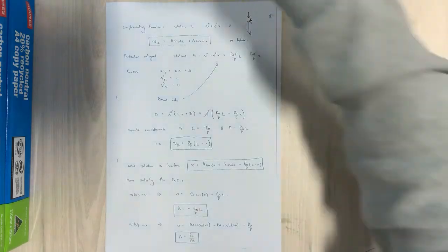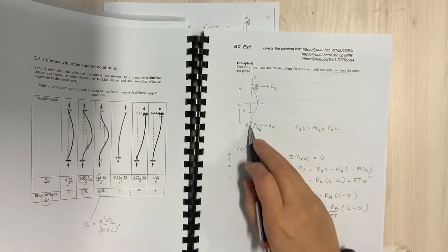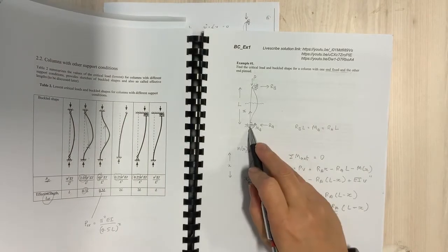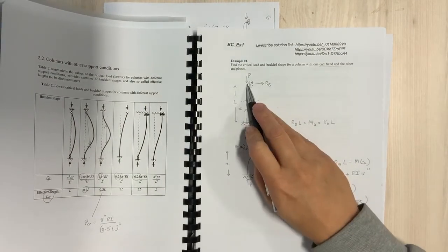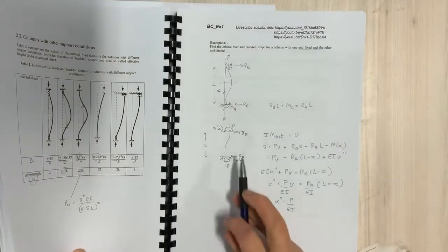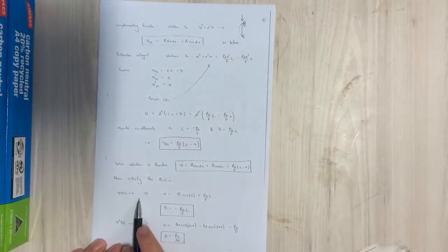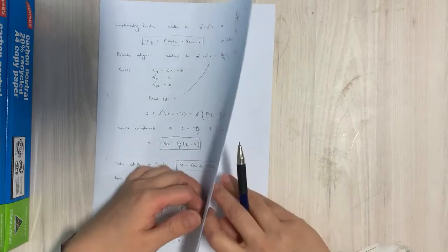boundary conditions. So the boundary conditions, as we had before: the deflection is 0 right at the support, and when X is equal to L, it's also 0. And then we've also got the gradient, or the rotation, here is 0 because of the fixed support. So you shove those into here, and then you can solve for your B's, and then you can solve for your A's.